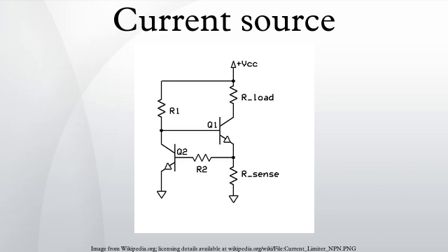Conversely, current and voltage sources can be connected to each other without any problems, and this technique is widely used in circuitry. Because no ideal sources of either variety exist, any current source can be considered as a voltage source with the same source impedance and vice versa. These concepts are dealt with by Norton's and Thévenin's theorems.